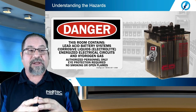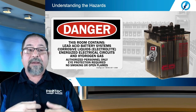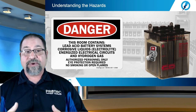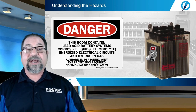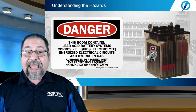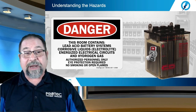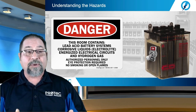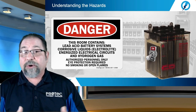Each individual cell may hold only around 2 volts, but when placed in a series string, the voltages will accumulate. Typical battery bank configurations found in substations and data centers will be 48, 120, 240, 480 volts, or in some UPS applications, 500 volts and greater.